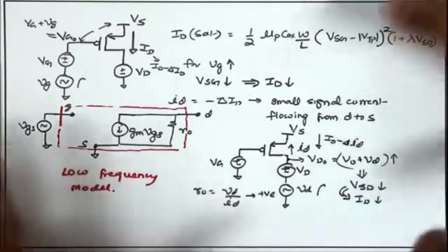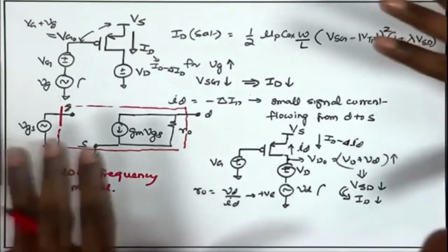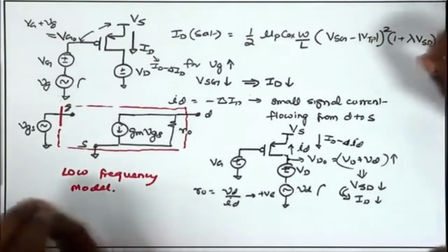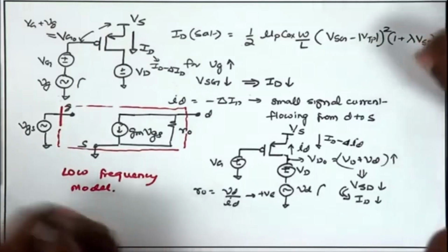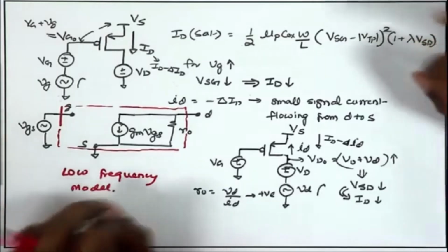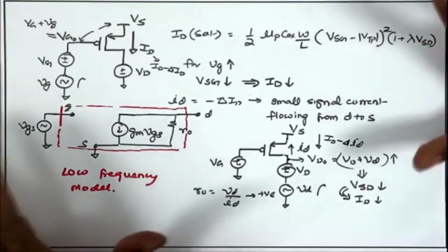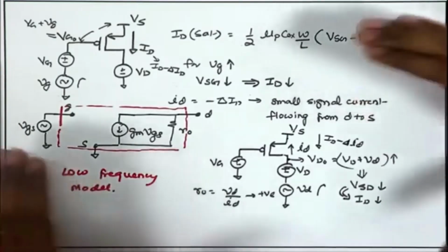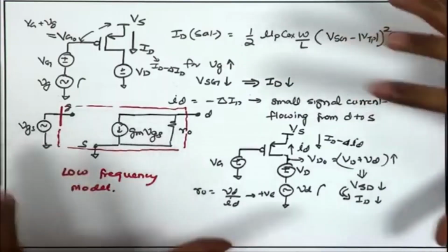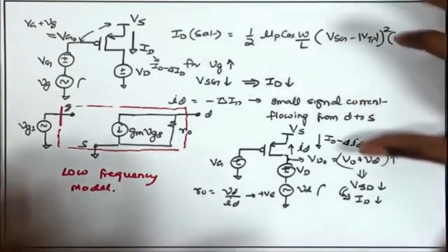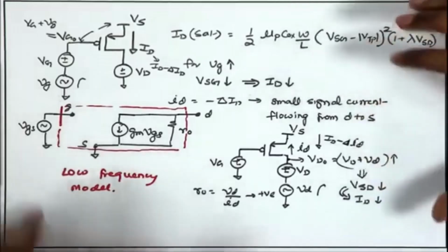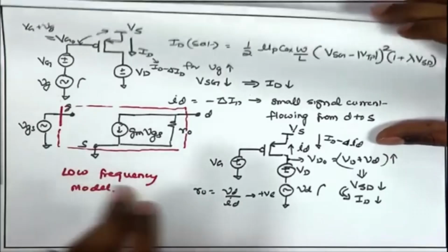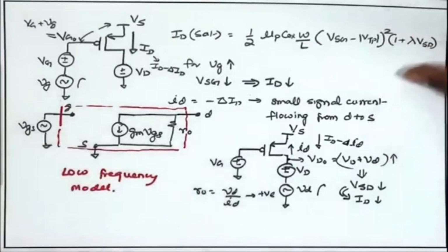Likewise, parasitic capacitances are ideally not supposed to be there. We do not want them, because they are going to affect or limit the performance of the MOSFET and the circuit we build with those MOSFETs. They are undesirable effects inherently coming from the device physics and the device operation of this MOSFET. So, let us first understand the basic mechanism of those parasitic capacitances, and how we define and quantify them and include them in the small signal model.